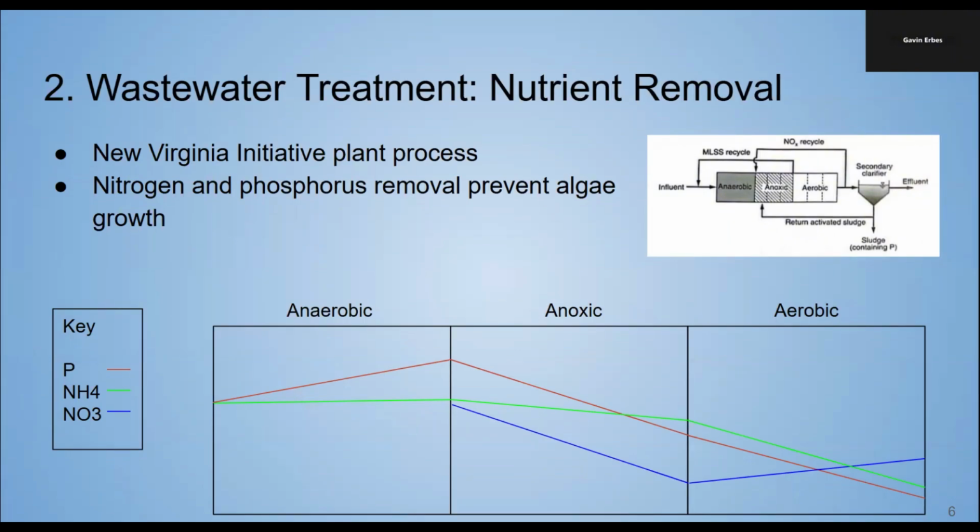This design also only has a detention time of 90 minutes for all zones and has been known to need a lower BOD to phosphorus ratio in the wastewater to still be effective. This is ideal because during wet weather events, the wastewater can get diluted and it can be harder to treat.